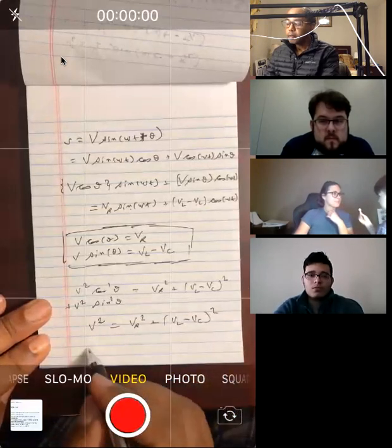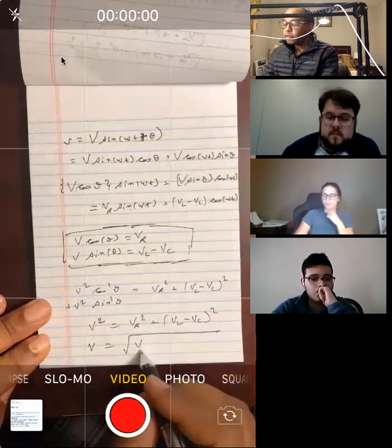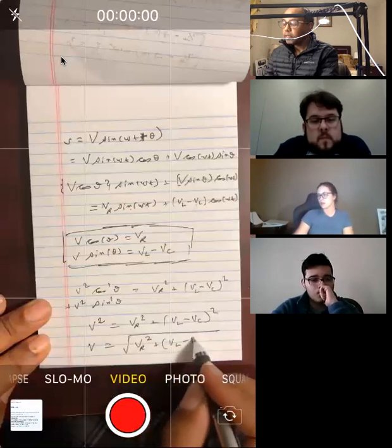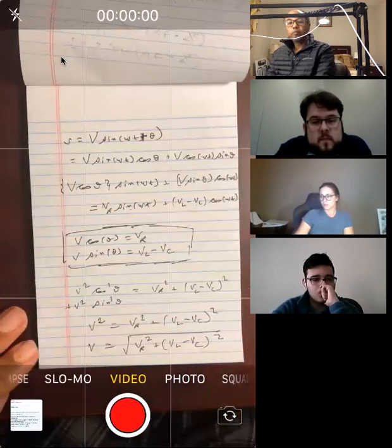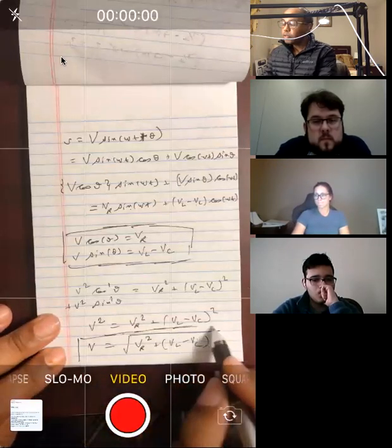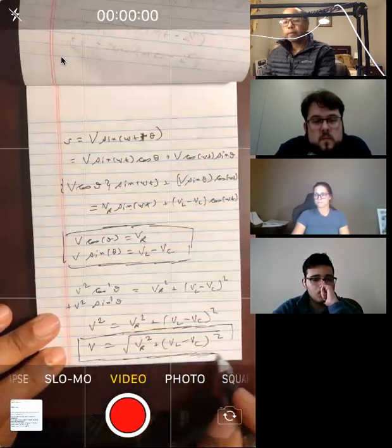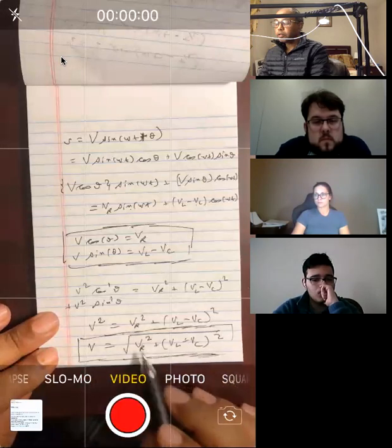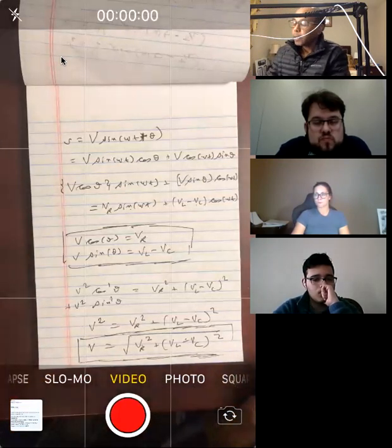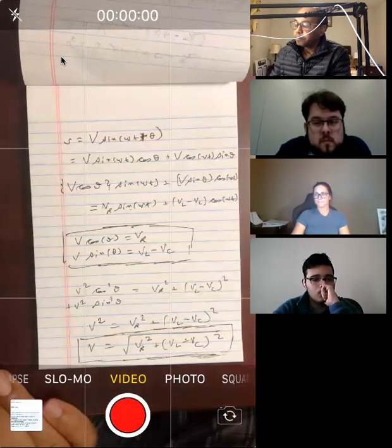Or you can say the amplitude of the net voltage is the square root of VR squared plus (VL minus VC) squared. Now remember, these are amplitudes, okay? The instantaneous values are added algebraically, but the amplitudes, you see, are related vectorially. This is perpendicular to the resistance. That's why I have the Pythagorean theorem over here, okay? All right, so that's how the amplitudes are related.